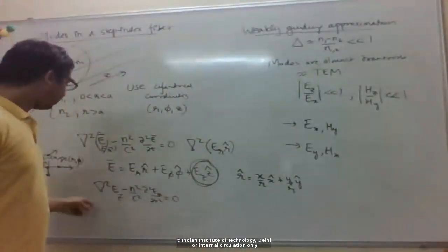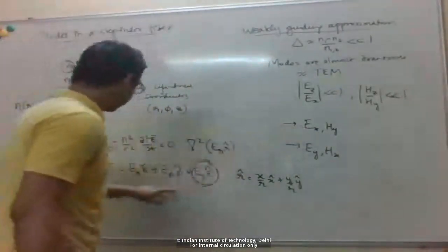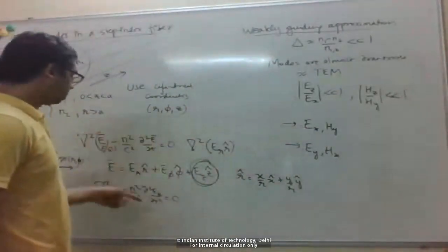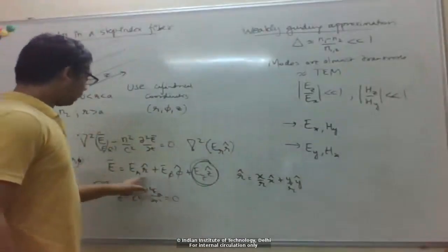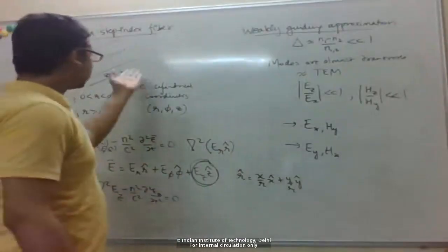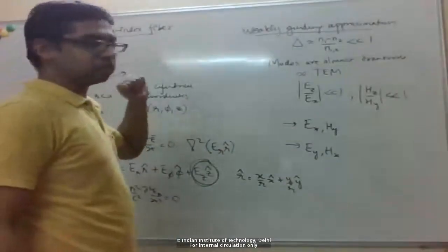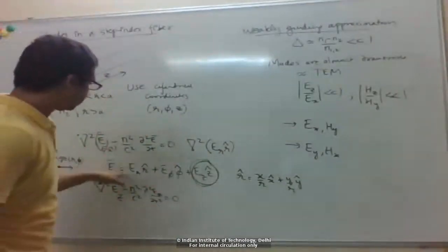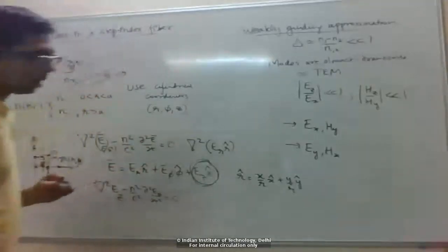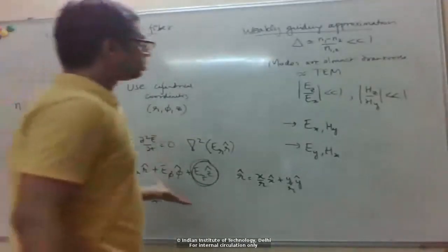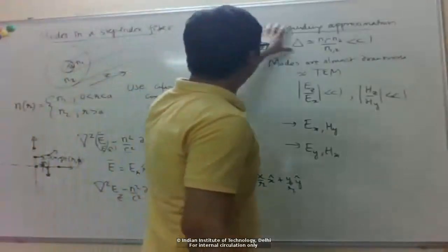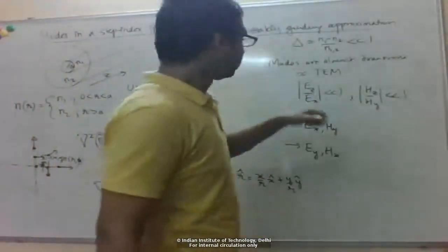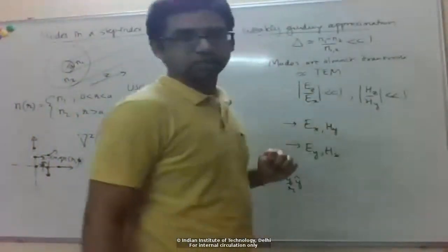So now we just directly solve a scalar wave equation in cylindrical coordinates. It's more complicated than the Cartesian coordinates, for example the slab waveguide, but it's not that complicated. But again, the thing to remember is that this is approximate, which only works in this weakly guiding regime where the fields are almost transverse.